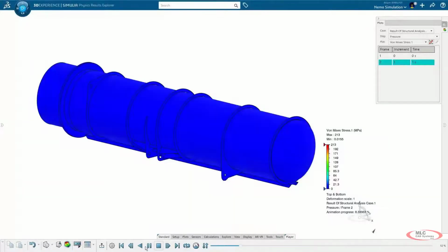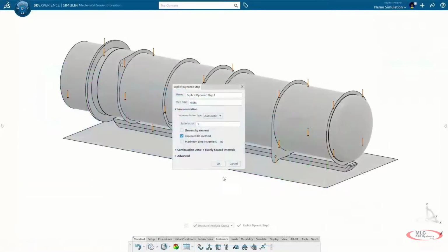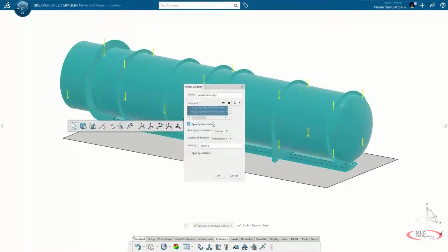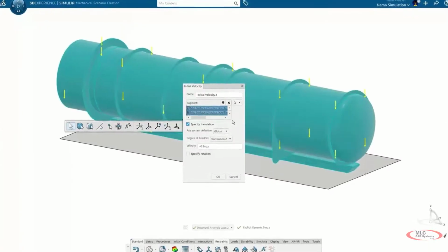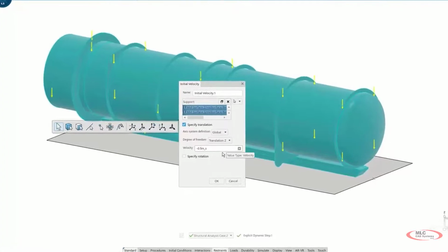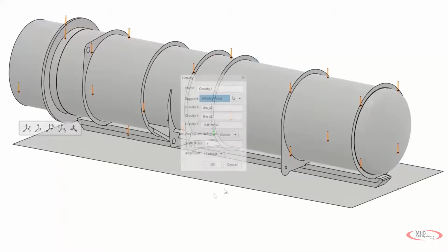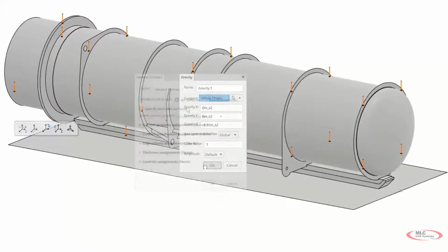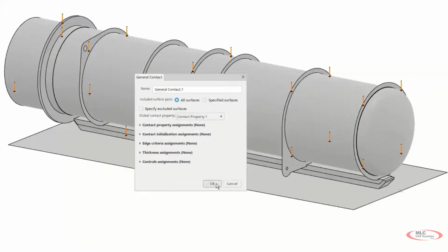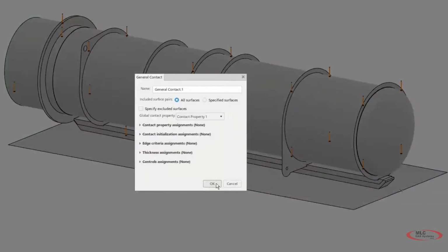The pressure load on the battery compartment happens multiple times throughout the life of the Nemo. Another loading condition that repeats is the impact of the skid landing during storage. Now, to simulate the secondary loading condition, Adam creates an explicit dynamic study to accurately capture the rapidly changing stresses from this landing cycle. So how exactly does the skid come in contact with the floor? Adam really lets the solver figure that out with one simple yet powerful general contact interaction.